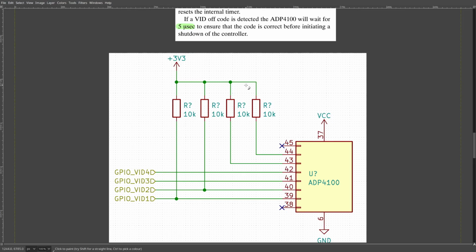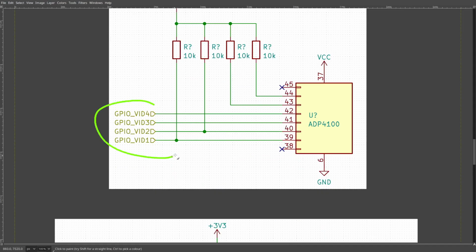And then once the GPU is on, it can use these GPIO pins to control the voltage on these pins, the vid pins, to basically put these as either high or low, and it can even most likely overpower these resistors such that they don't matter, and then it can control the voltage how it wants. Now you will notice something, that typically there is not a GPIO pin for every vid pin because we don't need one. And you can save space, less pins on the GPU used, less traces that have to go all the way across the PCB.